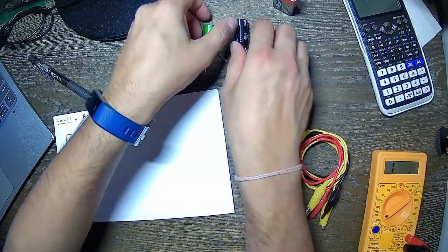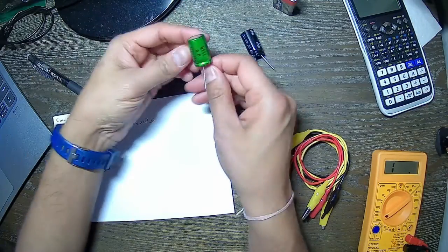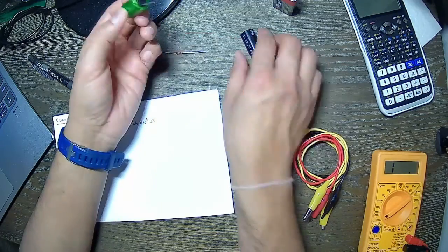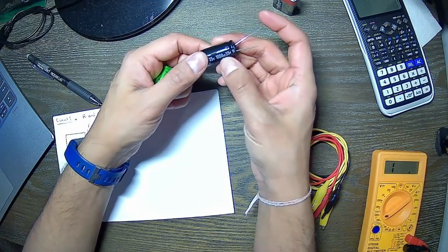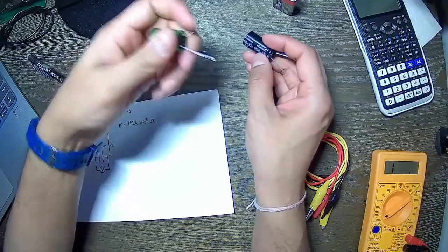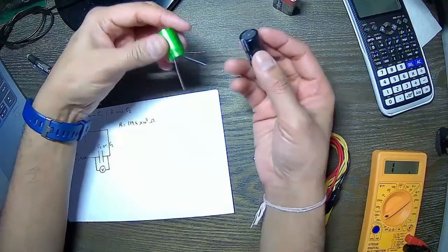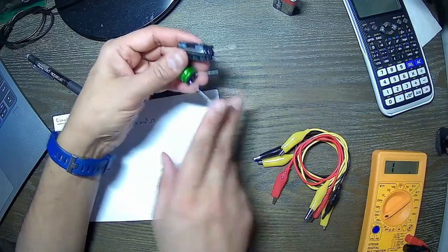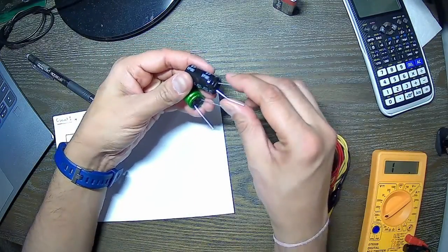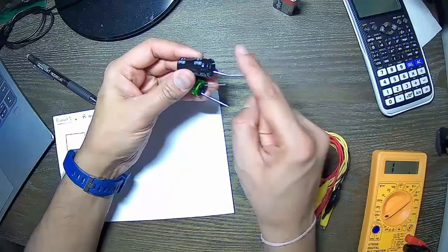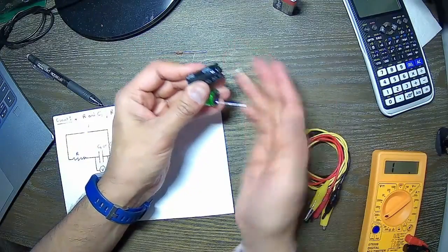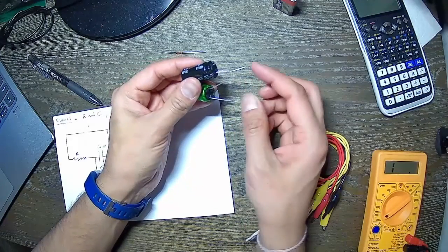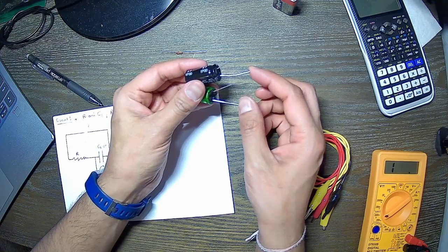And then I have two capacitors here. This one is listed as 470 microfarad, and this one is listed as 1000 microfarad. So the smaller one is my capacitor 1, the bigger one is capacitor 2. Now the two probes sticking out, these wires from the capacitors, one is longer than the other, as you can see for both. For each one of them, the longer wire represents the positive terminal of the capacitor.